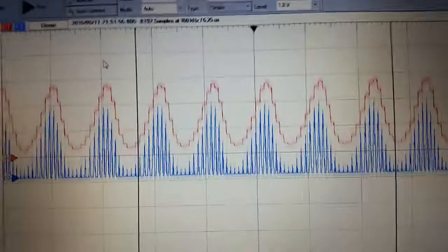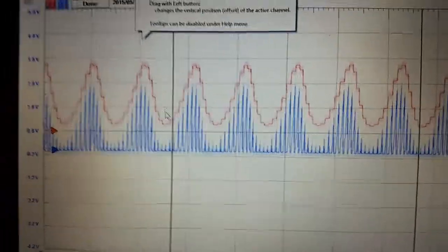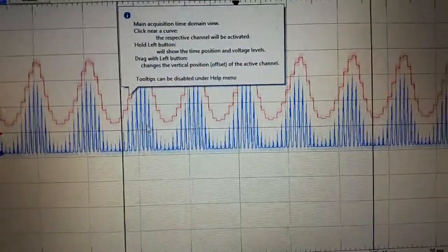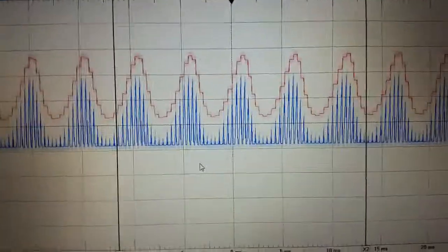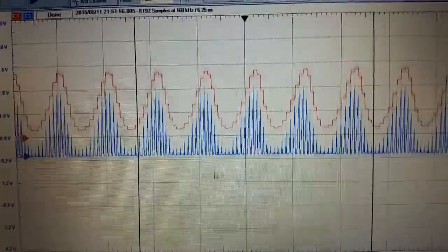We still see a sine wave being created, but it is not nearly as smooth. That is due to the data resolution limitations of our ADC. It is possible to speed this up if we used a smaller capacitor value on our sample and hold implementation.